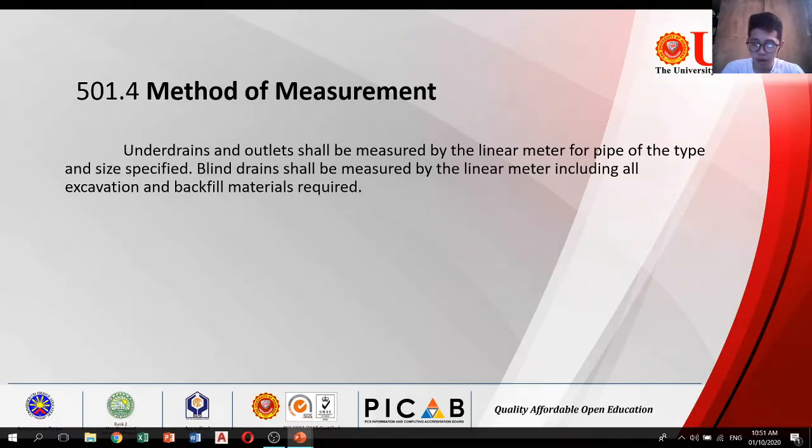So, granular backfill filter materials when specified in the contract as pay item shall be measured in place by the cubic meter, completed and accepted. Cross-sectional measurements will not exceed the net dimensions shown on the plans or as directed by the engineer. The excavation for under-drain pipe will be measured and paid for as provided in item 103 structure excavation.